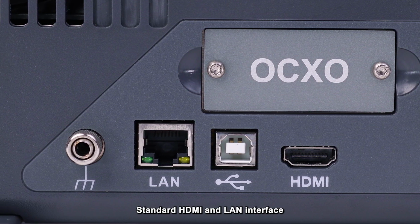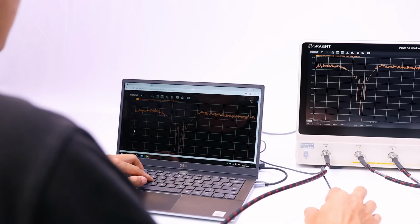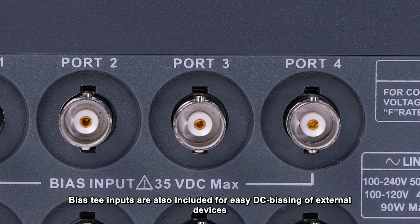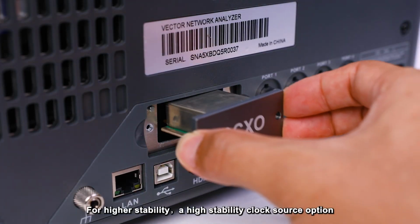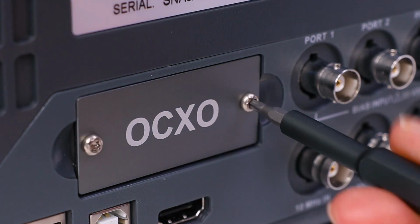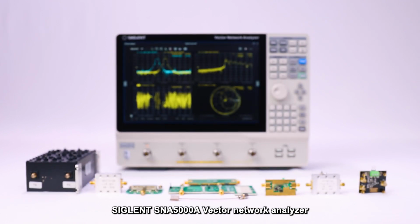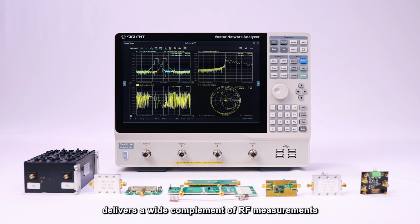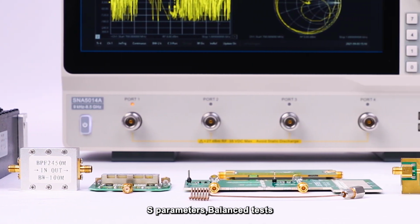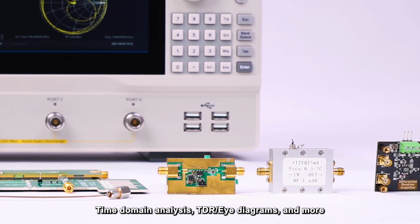Standard HDMI and LAN interface make it easy to connect, display, and control. Bias T inputs are also included for easy DC biasing of external devices. For higher stability, a high stability clock source option can be ordered later and installed easily on site. The SIGLENT SNA5000A Vector Network Analyzer delivers a wide complement of RF measurements, including S parameters, balance tests, time domain analysis, TDR and eye diagrams, and many more.